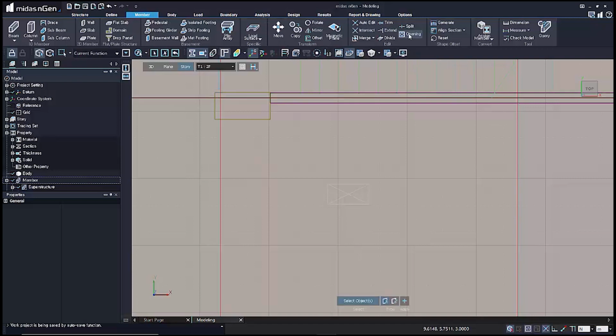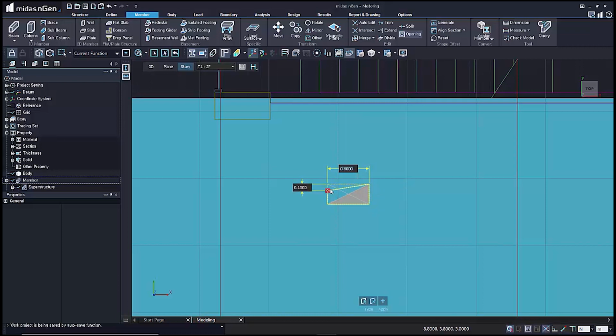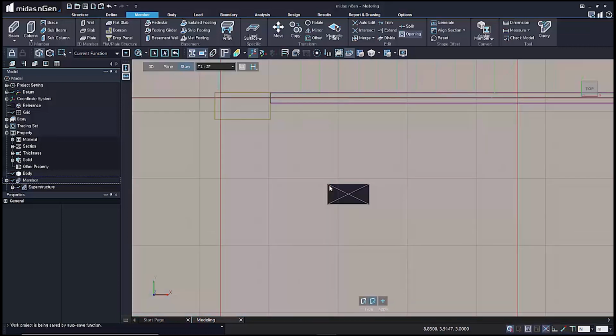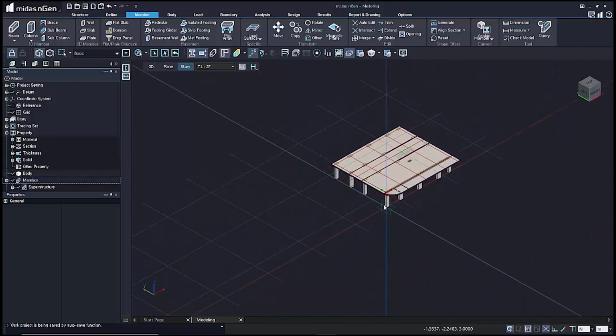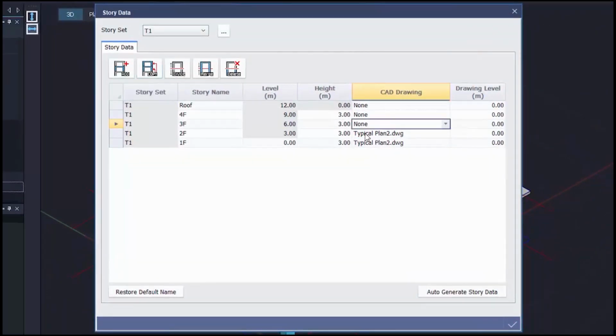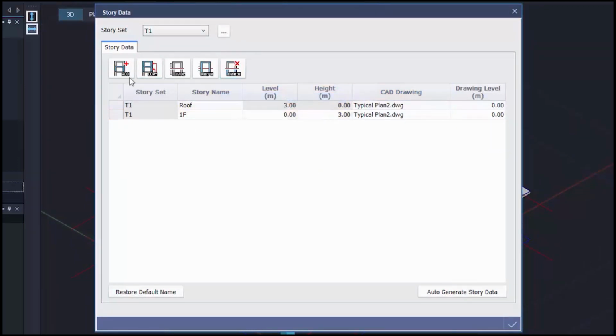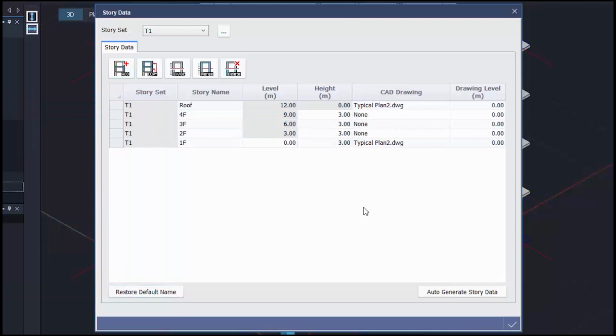In addition, the opening of modeling function is used to reflect the opening while viewing the drawing. Enter story data again and use the create members to copy and complete the modeling. You can use the copy function, but in this tutorial, we will use the add function.